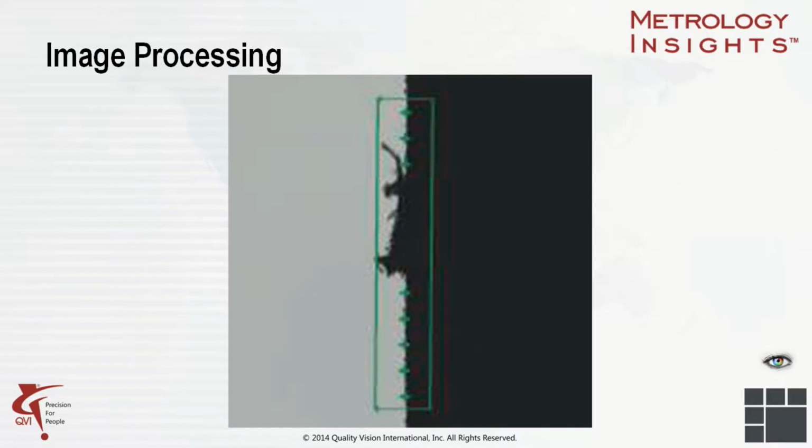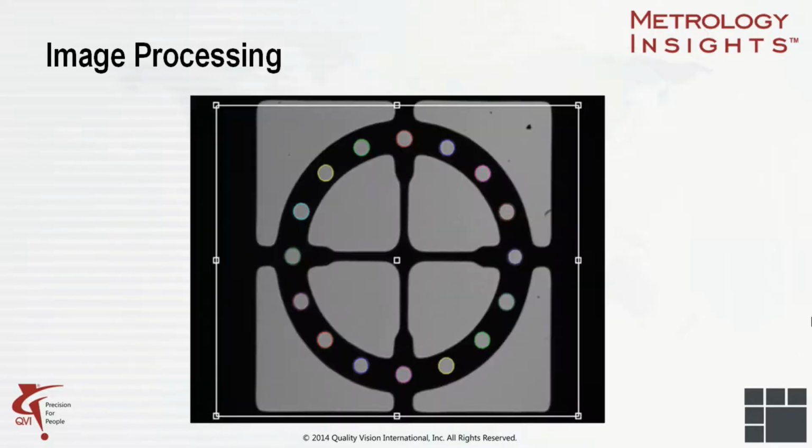We also see there is a defect of some sort, most likely dust or a burr, which can probably be easily removed and is therefore not important to the measurement. Image analysis tools enable us to filter out the dust and burrs so our measurement is not impacted. The settings used to determine what is a defect must be flexible so we can adjust them to suit the conditions of our part. In this scene, we're using what's known as a blob analysis tool.